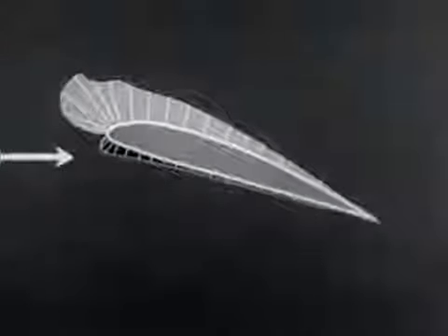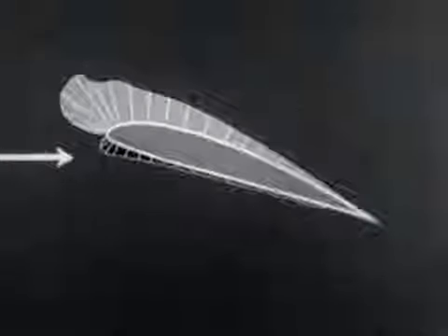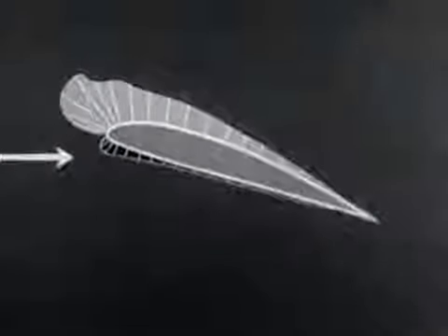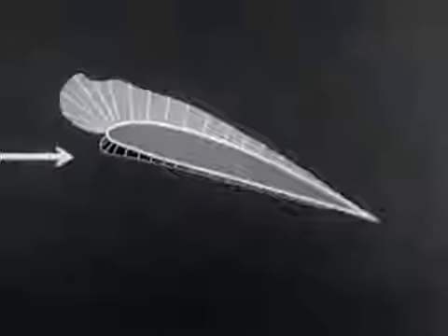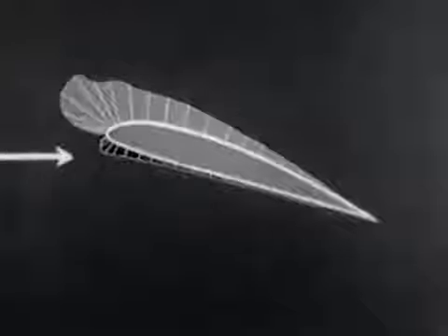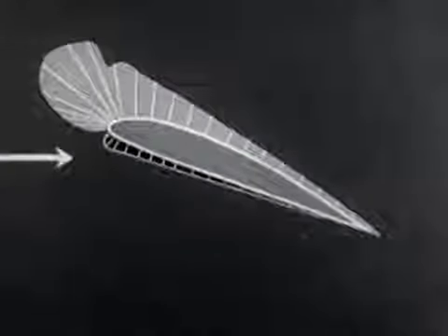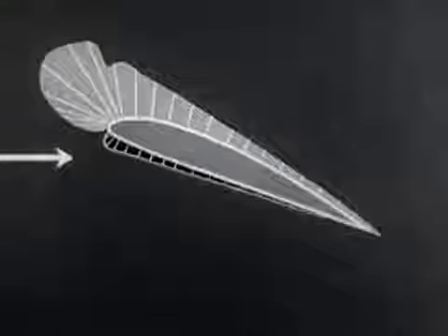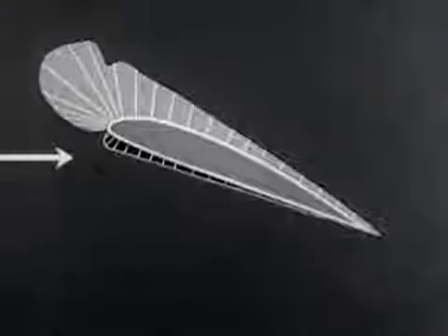By further increasing the angle of attack, positive pressures remain practically unchanged in both value and distribution, but the value of negative pressure continues to increase. At this angle of attack, the wing is well past its stalling angle, yet the positive pressures show little indication of change.